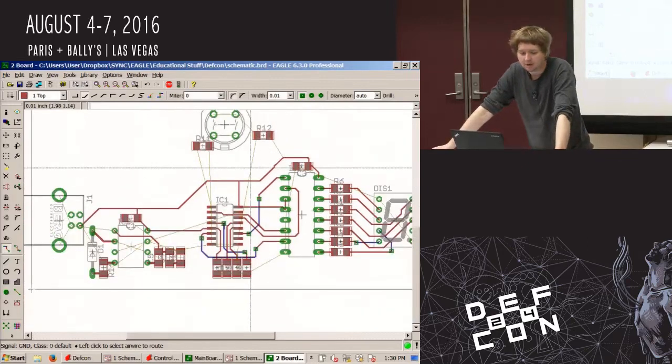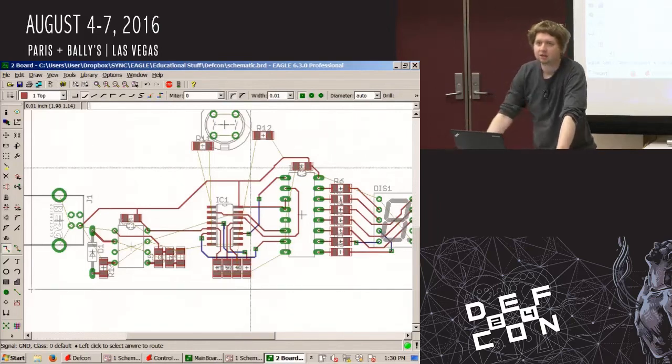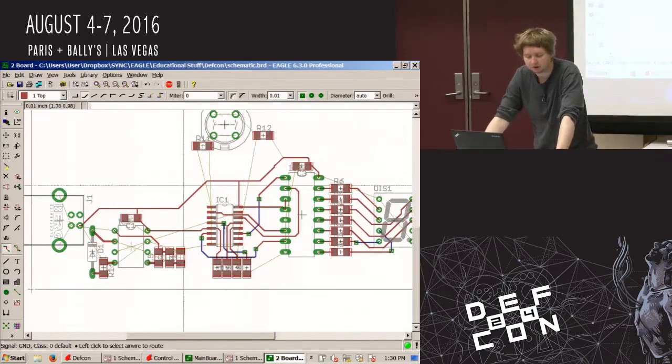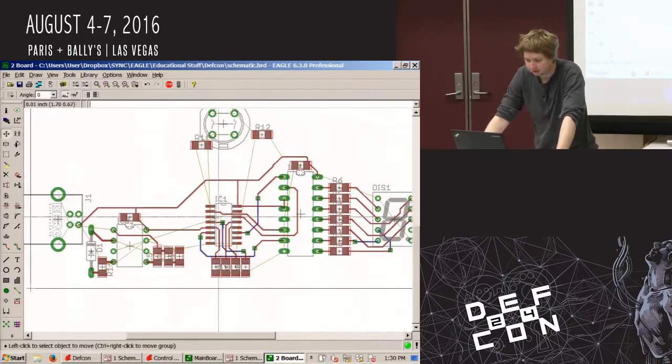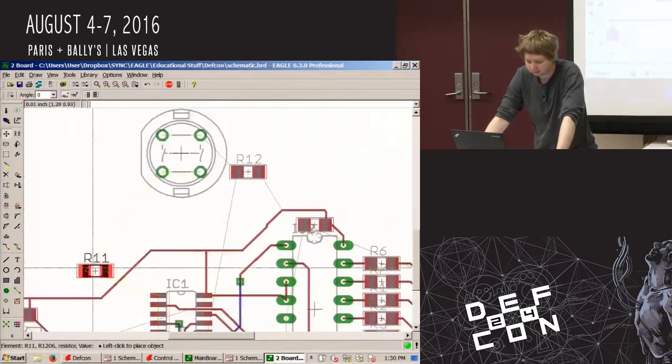But one thing to worry about with a ground plane though is if you're doing anything with high current or something that needs to feed back into itself, like a regulator or something like that, especially a switch mode regulator, you have to have the current loop as small as you can get it. Otherwise you can have a part that starts oscillating, and it'll take a while to figure out what's really causing that.